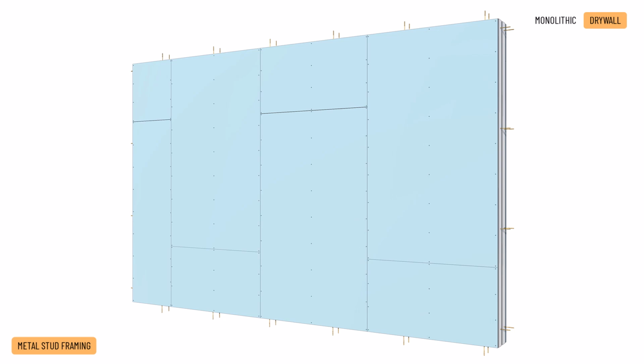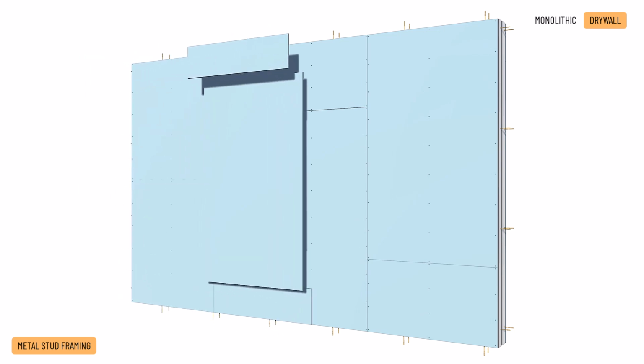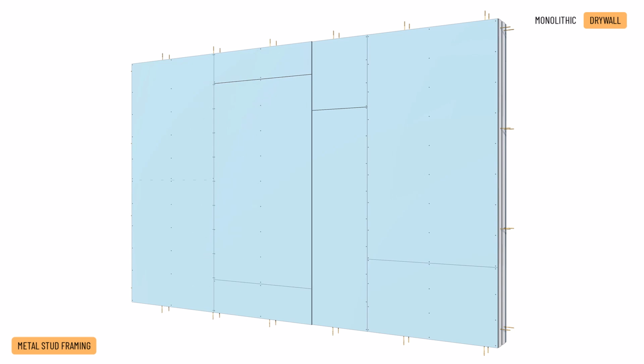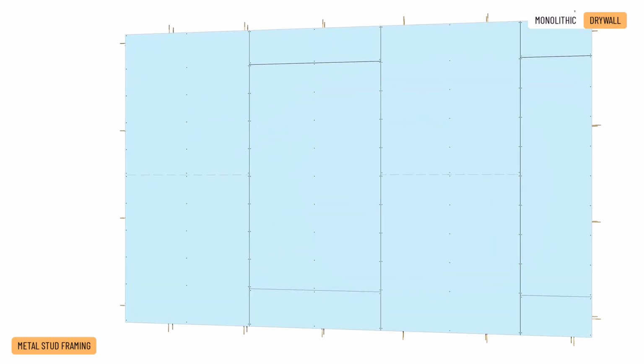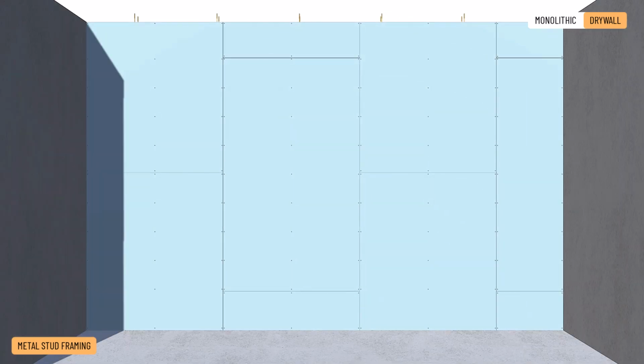The boards are cut to size so the two layers can be fixed together in a bond while avoiding a continuous horizontal gap running along the wall. This time, the boards are also spaced at the sides by 6 to 8 mm at the bottom and 2 to 3 mm at other places. The gaps are filled with a flexible filler such as silicone.